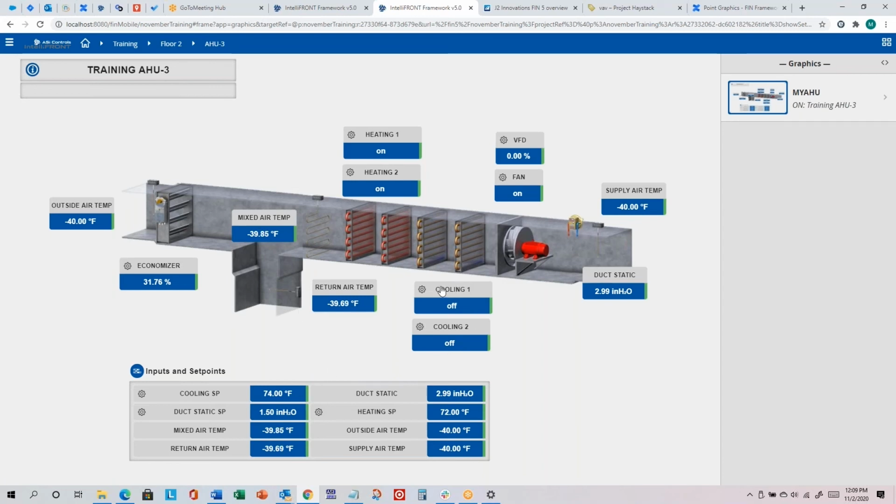And then you can test your animations. We didn't really have any animations on the VAV equip. You can do one for the damper. We don't truly track damper position for pressure independent VAV control. We just open the damper until we reach that point, and close the damper, if it's too high, until we reach that point. For graphics purposes, sometimes people just look at the cooling requirement.